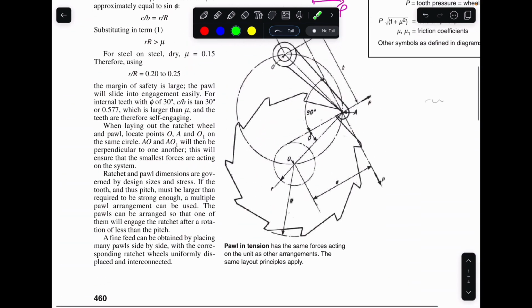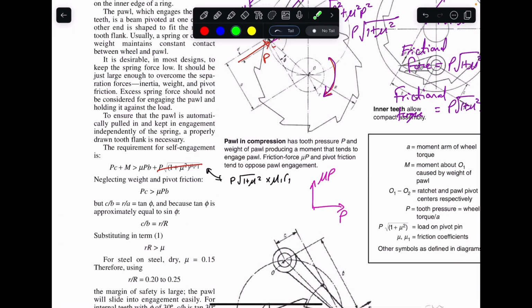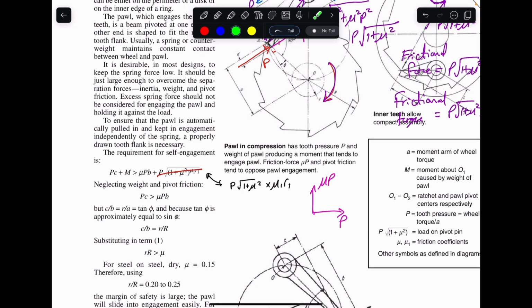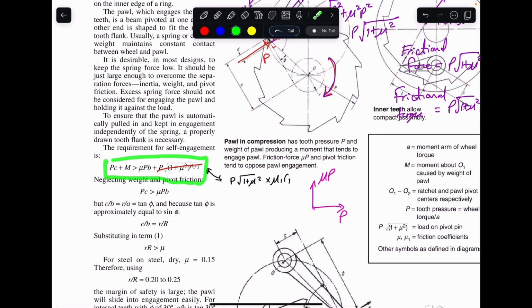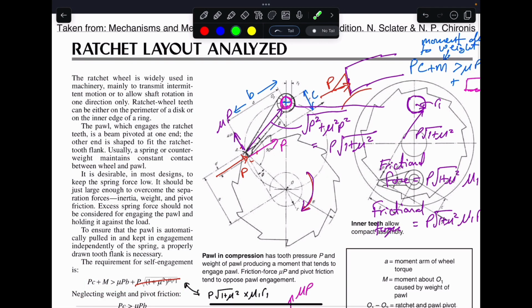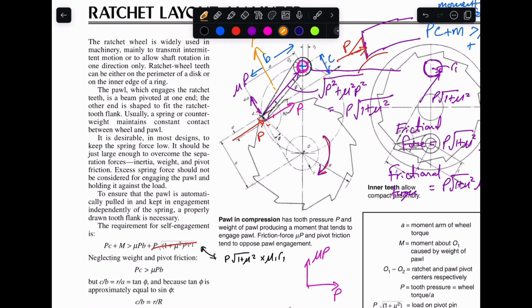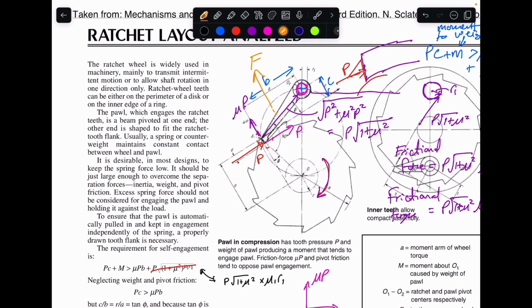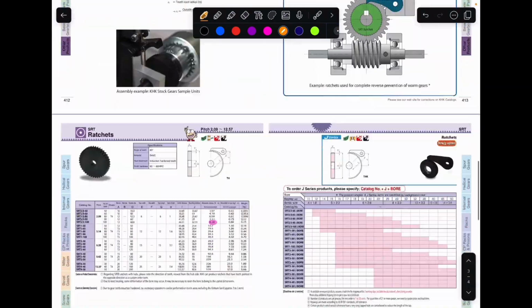Right, and that's for information, that lifting force at disengage will be a factor of this equation here. Right, so we could actually model it with a force. Let's just say we want to know how much force we need to lift the pawl to disengage. So we want to put a motor or a servo to lift that. Well, then you could go ahead and actually calculate that from this equation. Right, you just include F into your calculation, into deriving the equation. Right, so that just concludes this very short introduction to ratchet and pawls.